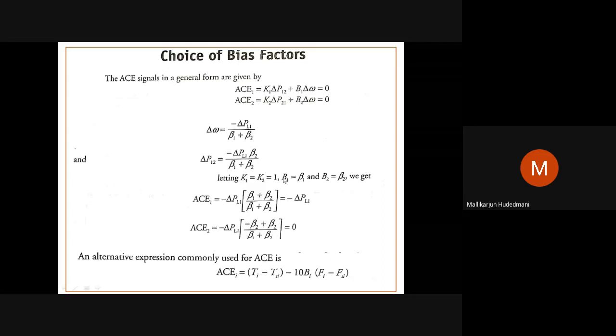like that. If I substitute in these equations, suppose the load change is in area 1. The intention is to show you that when the load change is in area 1, AS must be non-zero in area 1 and AS of area 2 should be 0. It should not compel the controller in area 2, because the load change is in area 1. Area 1 is responsible to work for that. To show how AS acts on the area, we can understand by inputting these data.